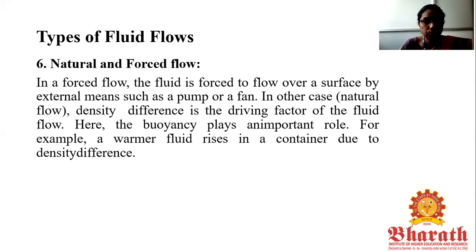Then natural and forced flow. In a forced flow, the fluid is forced to flow over a surface by external means, such as a pump or a fan. In the other case, natural flow, the density difference is the driving factor of the fluid flow. So buoyancy plays an important role in natural flow. For example, a warmer fluid rises in a container due to density difference. This is natural and forced flow.